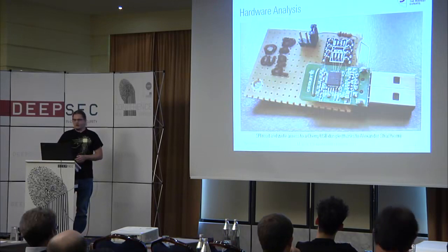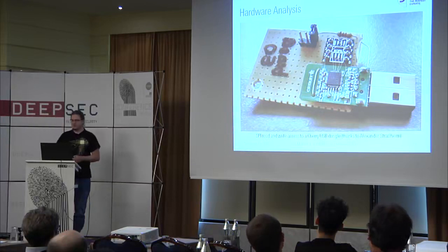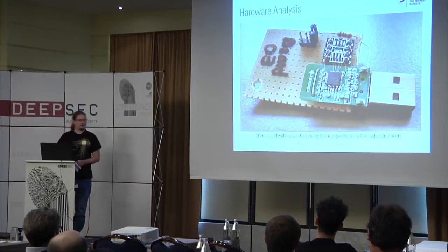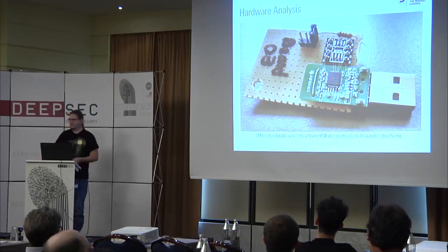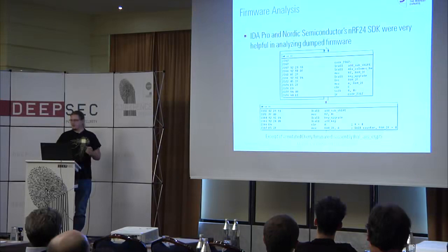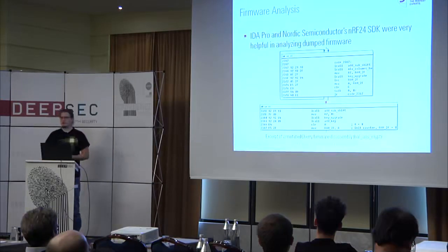A little bit more complicated was the dongle, at least the Cherry dongle. The pins were not accessible in an easy way. Fortunately, my dear colleague Alexander has a very calm hand when it comes to soldering, so he was able to solder these very thin wires on there, so we were able to access the SPI interface. Firmware analysis is pretty much straightforward. You can load that into IDA Pro or something similar that is familiar with the 8051 instruction set, and you can decompile and reverse it.